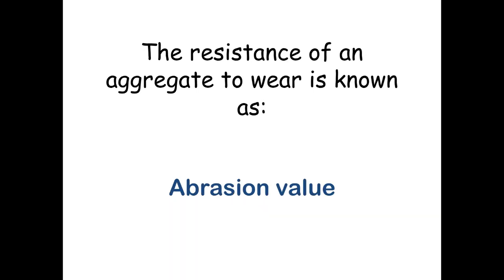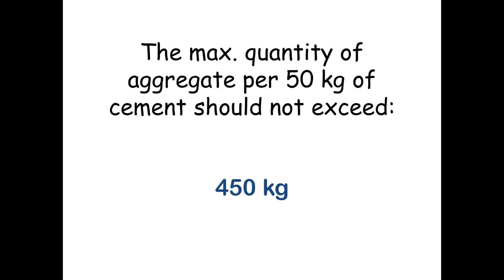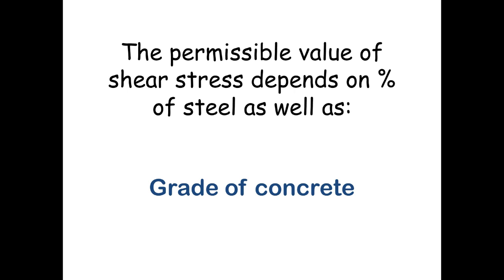The resistance of an aggregate to wear is known as abrasion value. The maximum quantity of aggregate per 50 kg of cement should not exceed 450 kg. The permissible value of shear stress depends on percentage of steel as well as grade of concrete.